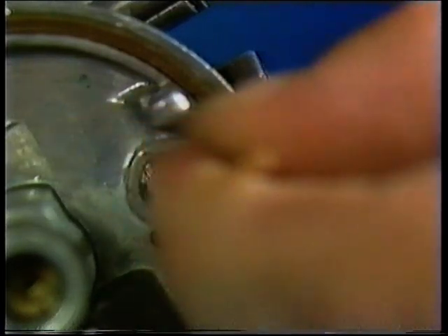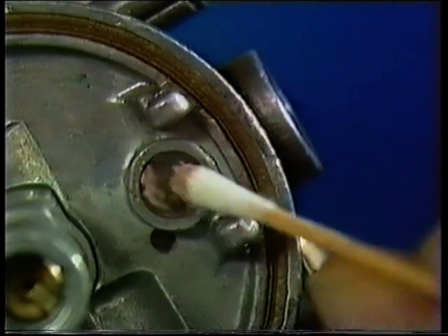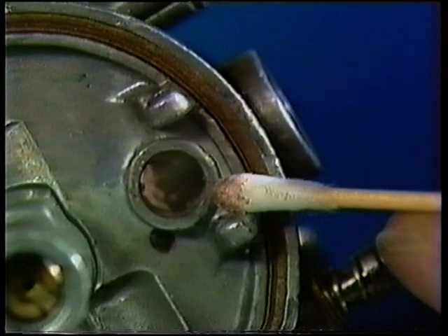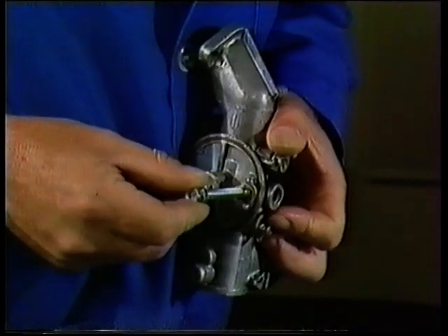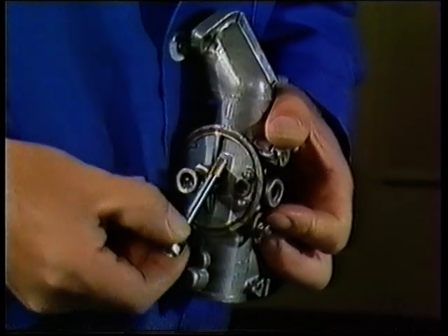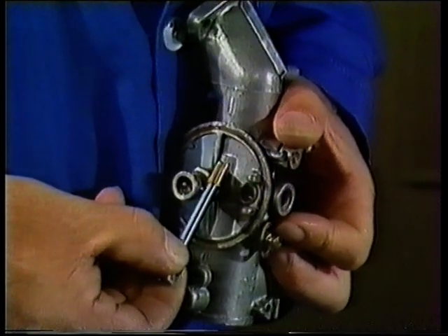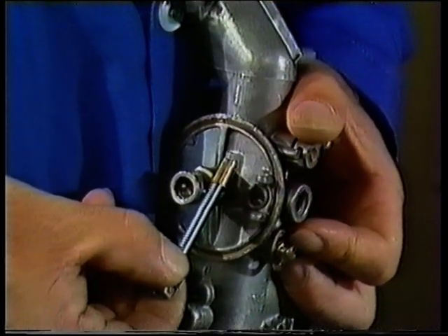Take the inlet seat, for example. Dirt and debris can hide behind the seat, only to cause leakage in the future. If the seat is removable, do it now. Proper procedures for seat removal are described in your repair manual.